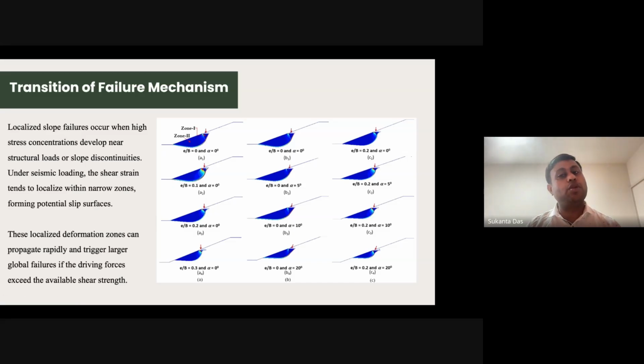So we should also think that because of structural asymmetry, your soil mass reaction, which is indirectly relevant to the bearing capacity, is going to reduce. Again, the buildings may become very vulnerable. Eccentricity has an influence on flat ground, but it is more complex when you have sloping ground. I will explain again why it is more important.